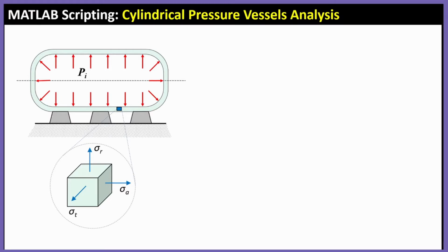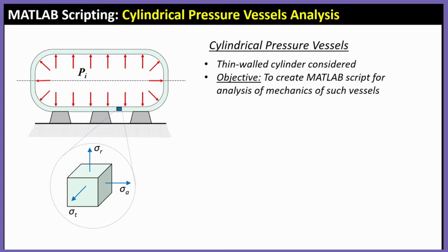Every point in this pressure vessel will be subjected to three stresses: one being the radial stress, another being the axial stress, and the other being the tangential stress. They're acting at the same time during the operation of this. This is why it's really important to understand what these values are and to be able to use them if you're going to design a pressure vessel.